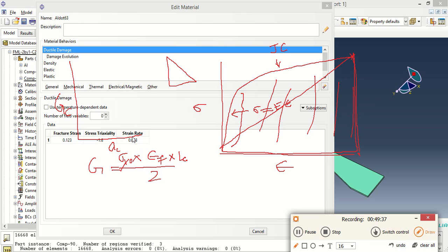So what is your crack length and what is your energy? You do a test, and in that test your data is obtained, and with respect to that Gc is obtained. So that is one way of obtaining the fracture energy, but that fracture energy is very low with respect to the amount of fracture energy inside the load displacement curve.